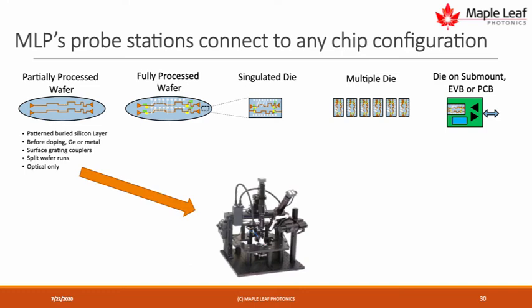You can make sure that the losses are correct. You can make sure the backscatter is correct. If you see crossed waveguides, you can evaluate their crossing. And if it turns out that something is off or off by enough, you may choose to halt the run and start over again. And you don't have to process the entire wafer to get this insight.